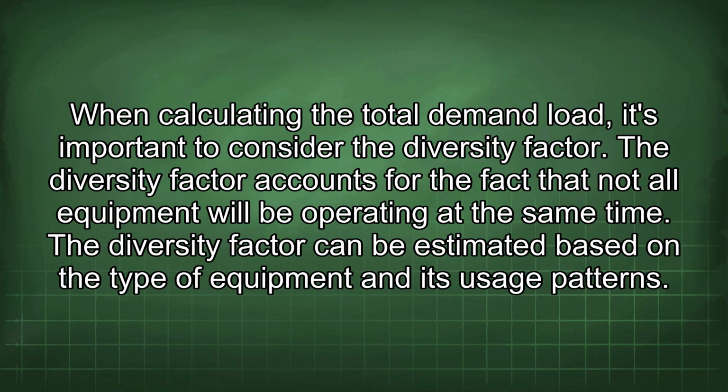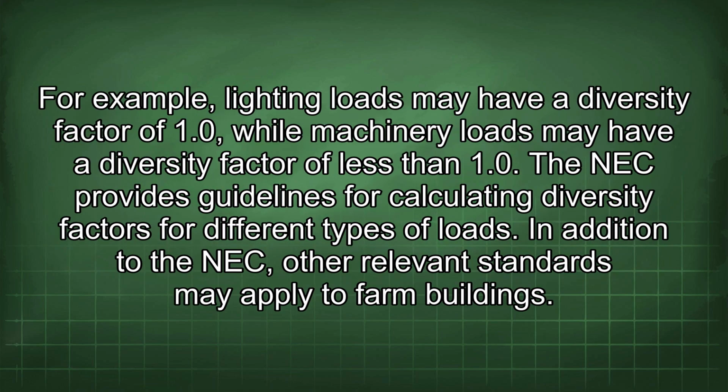When calculating the total demand load, it's important to consider the diversity factor. The diversity factor accounts for the fact that not all equipment will be operating at the same time. The diversity factor can be estimated based on the type of equipment and its usage patterns. For example, lighting loads may have a diversity factor of 1.0, while machinery loads may have a diversity factor of less than 1.0.